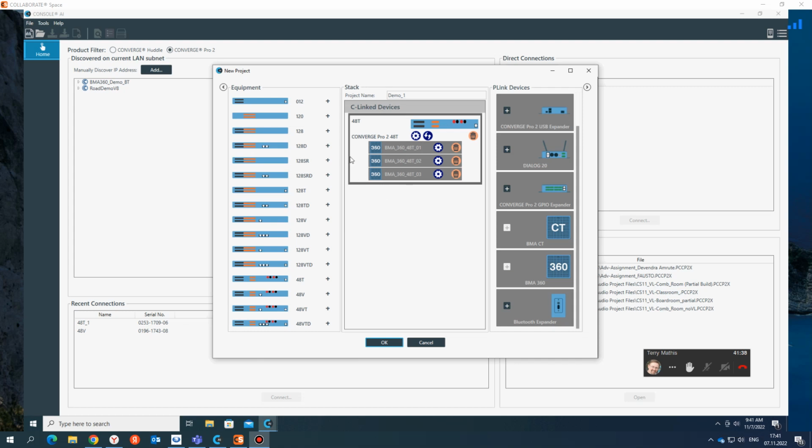By the way, even though you may not think too much about it, this is a big thing compared to some other manufacturers. You go to other manufacturers, you add 1 DSP here, you can only put 1 beamforming mic on it because they need the processing of that DSP to work. So then if you wanted to have more, you got to add another one and another one. So it adds a cost factor to your project file. In this case, only 3 can be used per DSP.